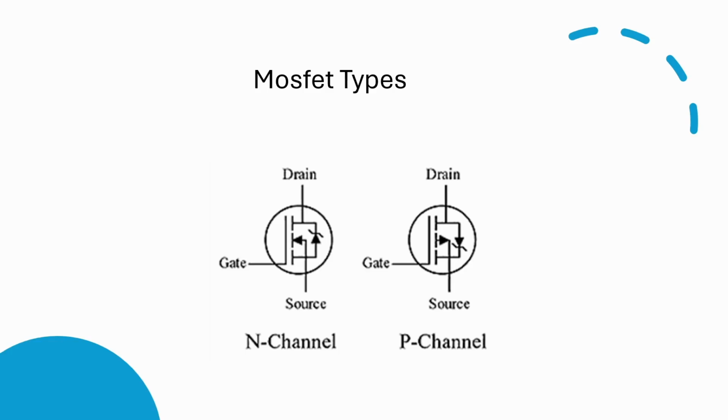The idea here is that whatever your load is, whether it be a motor, solenoid, LED, etc., one side is connected directly to the positive or negative, and the drain of the MOSFET is switched to complete the circuit and allow power to flow to your load.